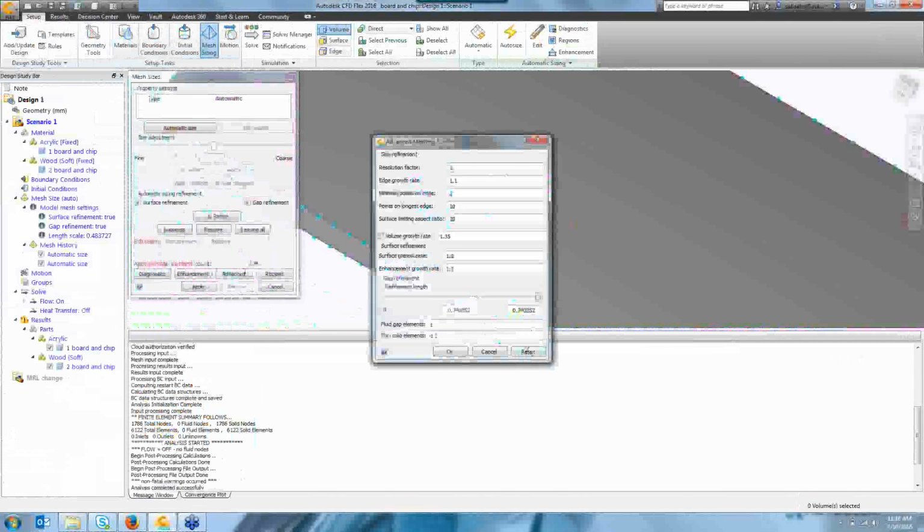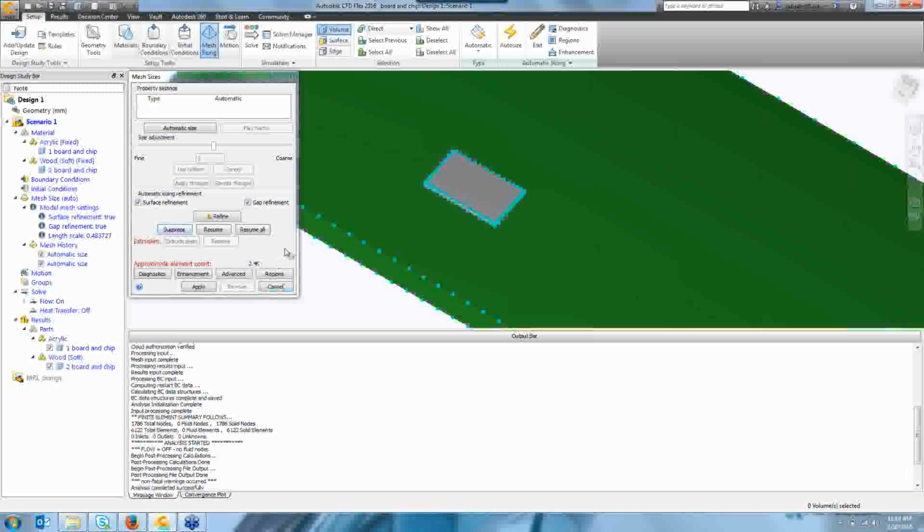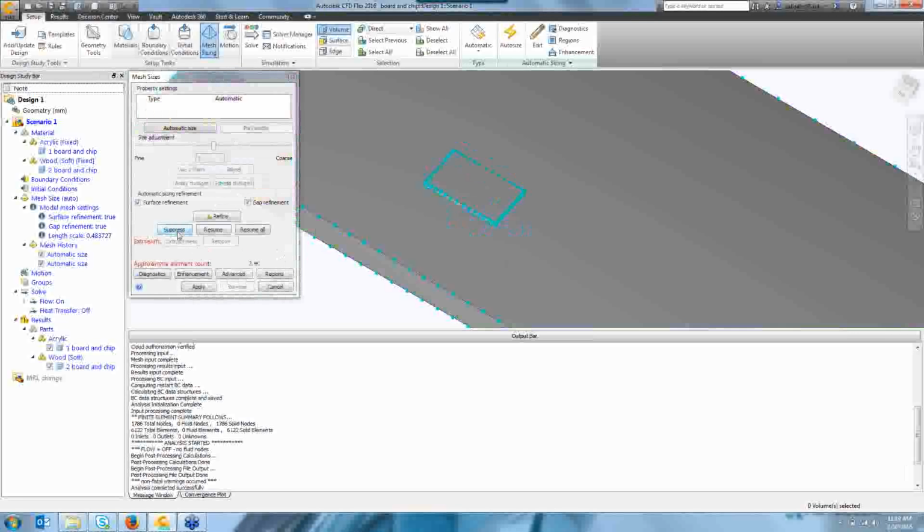Another thing that I guess might be worth noting is the suppress. If you don't have heat transfer in something, you should always suppress it. All of the surfaces will still be accounted for. I can run a quick model if anybody wanted to see it, but essentially you're just looking at a cutout in the model so that flow would be forced to go around that part when it's suppressed from our meshing.